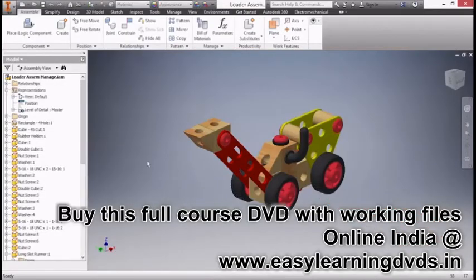In this video, we're going to take a look at assembly and management techniques inside of Autodesk Inventor. Here I have a loader assembly manage IAM from our working files directory. And this is a completed design that has all of my IPTs put together. They've been assembled using assembly constraints, which basically hold our parts together. So we can define how these things will come together in the overall arrangement by use of geometric rules and conditions we apply to our model.